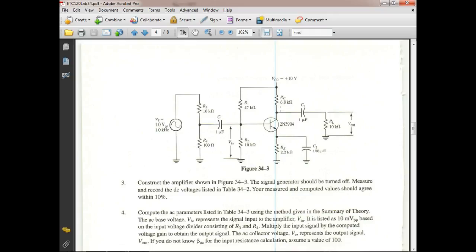What sets the emitter bias? Well, the emitter bias is set by that voltage right there. It has nothing to do with that capacitor. All that capacitor does is change the gain. When we calculated these voltages back in your worksheet, we didn't even have a capacitor there. So what would it do to our bias voltage? It's not going to do a thing. They're going to stay exactly the same. You understand that?